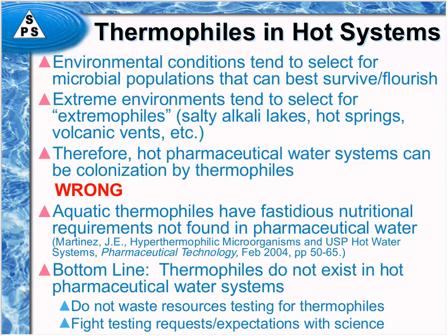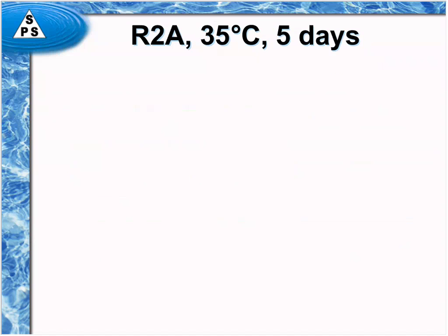So please do not waste your resources testing for thermophiles. And if you have some unreasonable expectation from an auditor or even from FDA, fight that request with science. Reference that article. Do whatever you can to avoid this senseless testing and waste of resources, because thermophiles do not exist in these water systems.